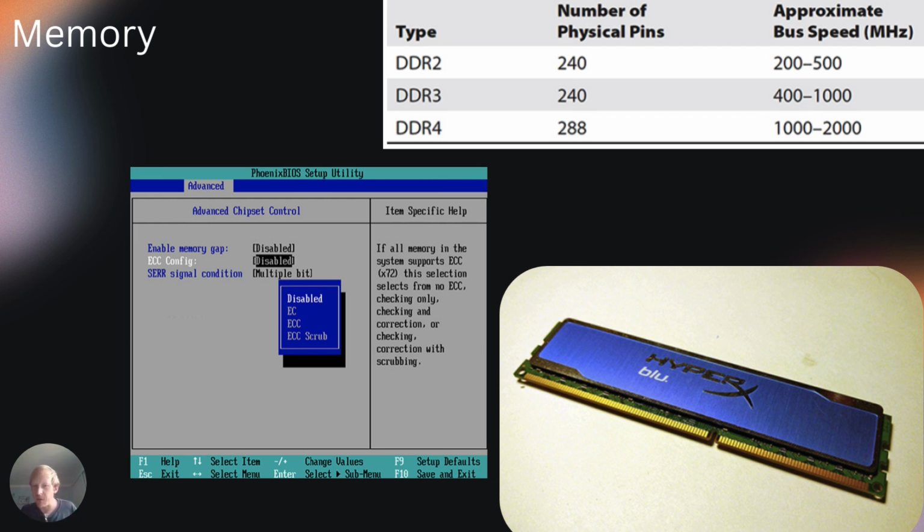How that happens is this type of memory chip has the added capability of detecting and fixing errors at the bit level. So if it's a 0 or a 1 that's not correct, it will correct it. It does this by using an extra bit of information, called the parity bit, for each group of memory bits. Although most non-ECC modules can detect memory errors, they don't do anything about it.